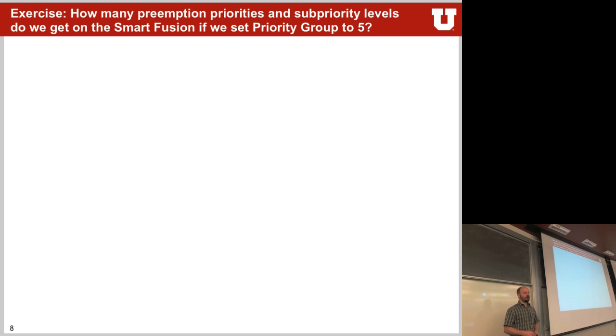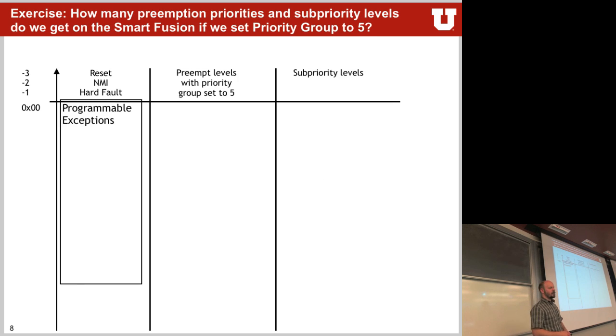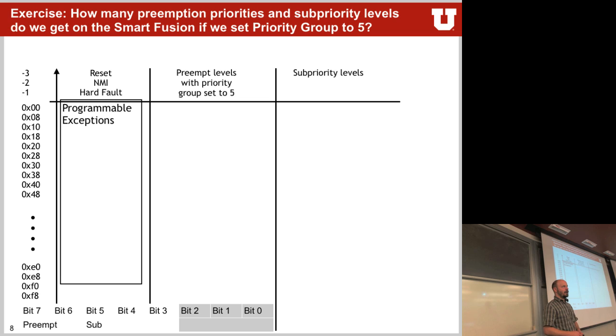Didn't you say there are 15 defined interrupts on the Cortex M3? ARM defines 15 interrupts that have to be certain specific interrupts that happen. And then the rest are implementation specific. They are per chip specific. So they are usually used for peripherals.